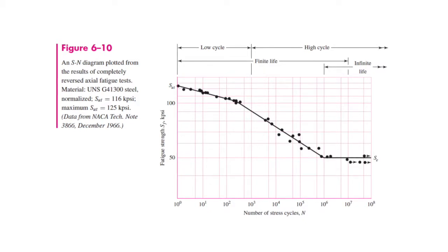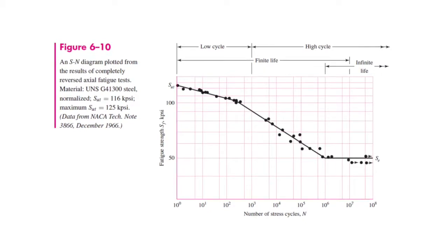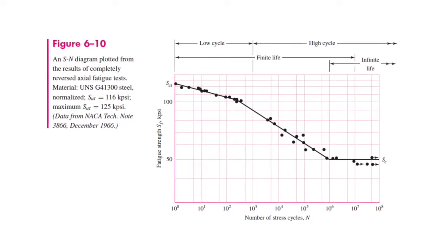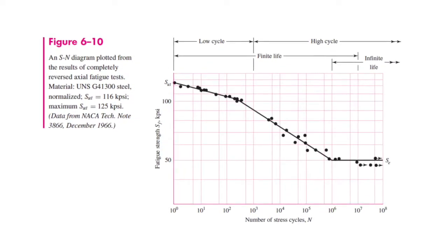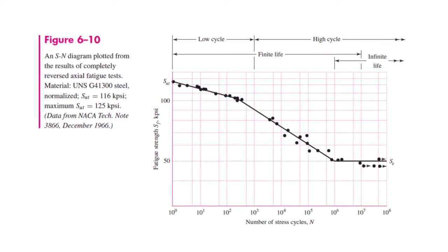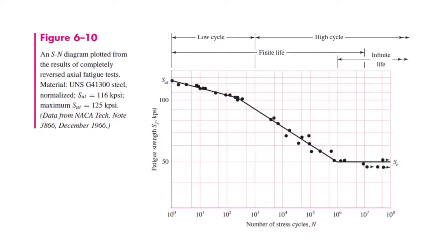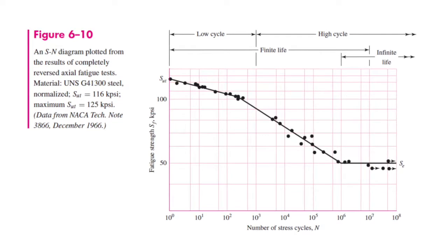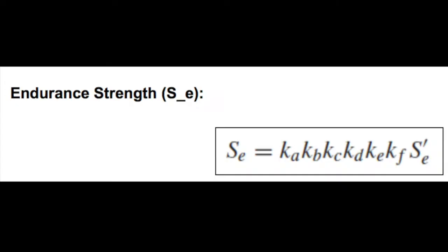The table shows that the failure stress tapers off and approaches a constant value as the number of cycles approaches infinity. The stress at which the number of cycles approaches infinity is known as the endurance limit. If the component's max stress is below the endurance limit, it is expected to survive an infinite number of load cycles. Determining the endurance limit is typically done empirically.